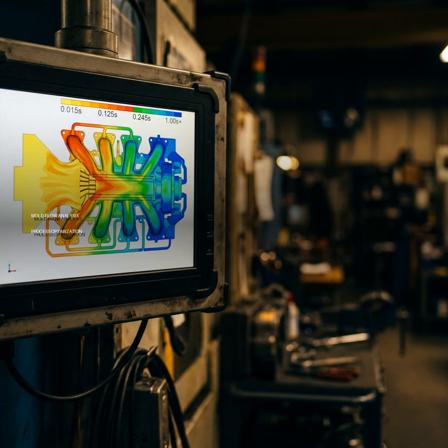And nozzle pressure. Nozzle pressure data helps us understand the flow front progression, any patterns, and how consistent the pressure is. Uneven distribution can lead to quality issues, like flow imbalances or air entrapment. It helps us optimize injection speed or melt temperature.